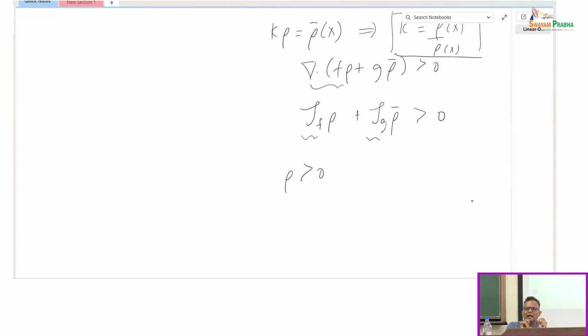So what happens because of that is you get this value function v, which is a function of x. It is telling me what is the cost if I find this value function, which is coming from the solution of the Hamilton-Jacobi equation. What is the cost that I will incur if I initialize the system from that initial condition x? That's the meaning of the value function.